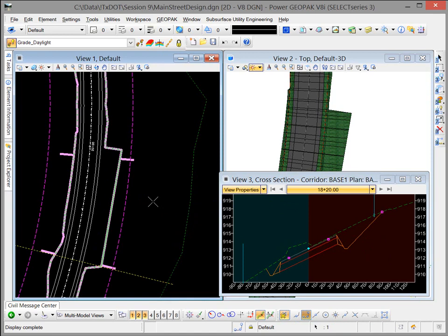So this is very nice. The only thing you have to be careful of is if your back slope has multiple solutions here, and you have the override going from different point names, it will only be able to pick one point name at a time. And so if you had multiple solutions through your range and you see results that don't line up all the way through, it's because you're getting different end condition solutions with different points.